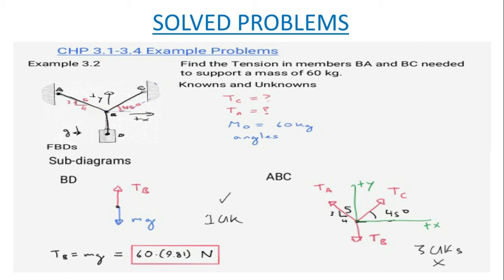Now the most important aspect: in previous lectures I have told you that you have to draw the free body diagram of your system. So B is the focal point. One cable is going towards A under tension TA. The other cable is going towards C, with tension TC. For TC, they have made our life very easy, as they have given theta as 45 degrees.